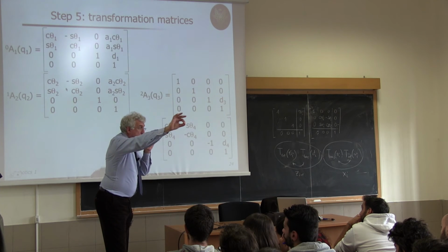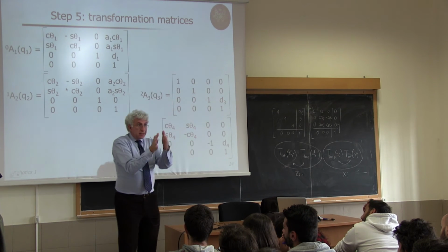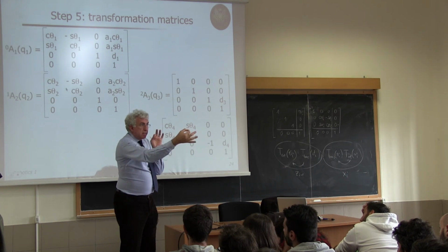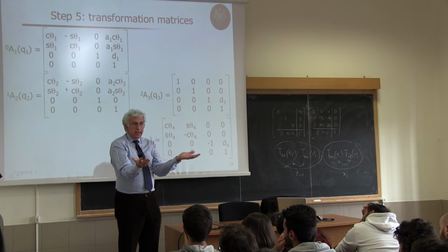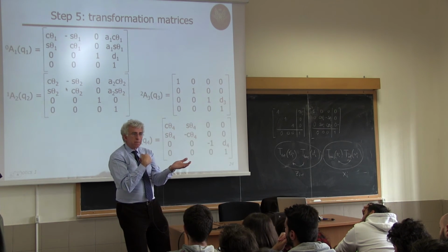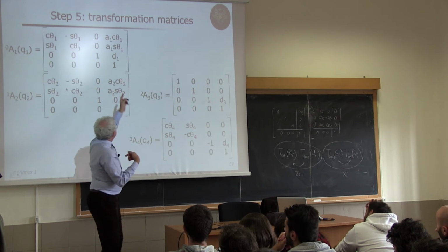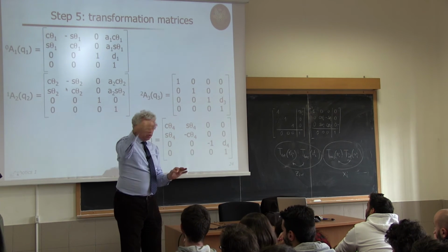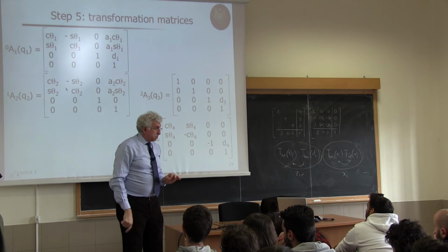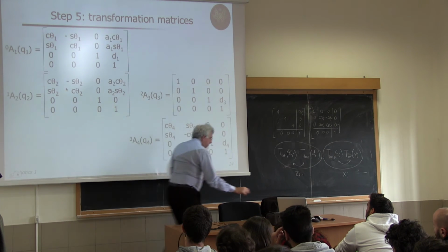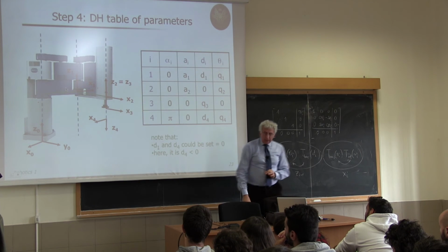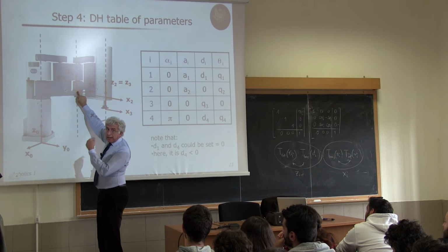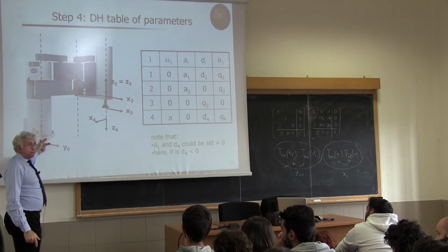Then it has to move by A1, but since link 1 is changing with theta 1, this length is divided by sine and cosine of this angle, as seen from frame 0. If I write the same vector, pay attention, the same vector from origin to origin, in frame 1, let's do this exercise. In that matrix it is expressed in this frame.